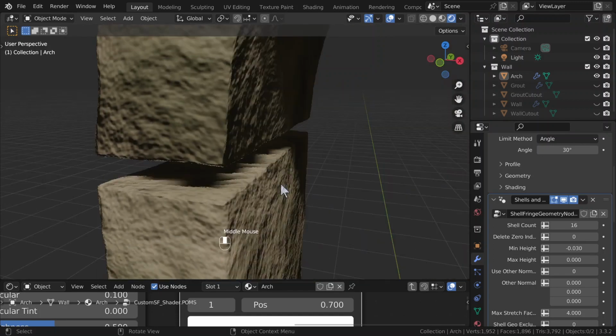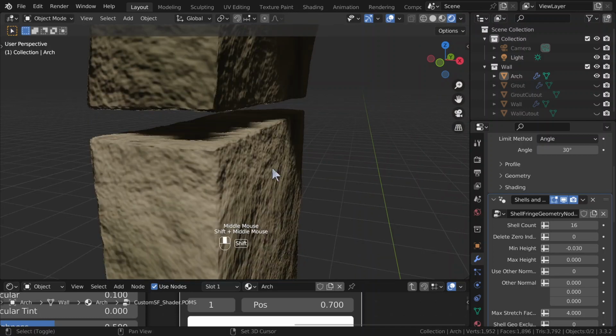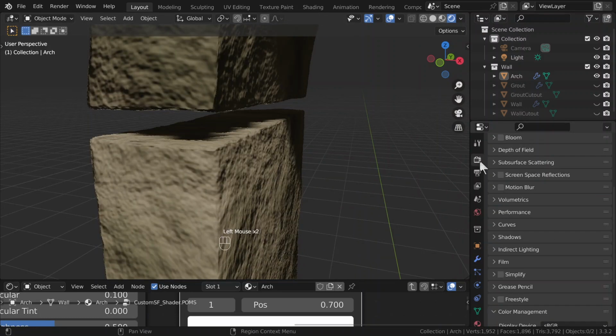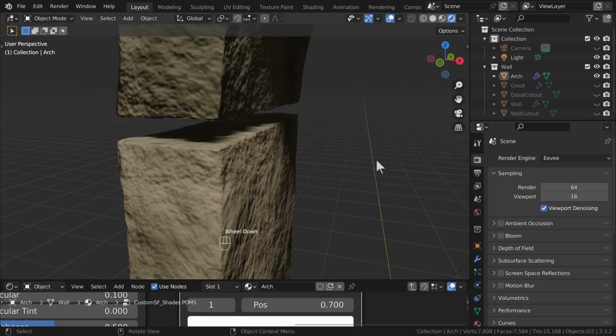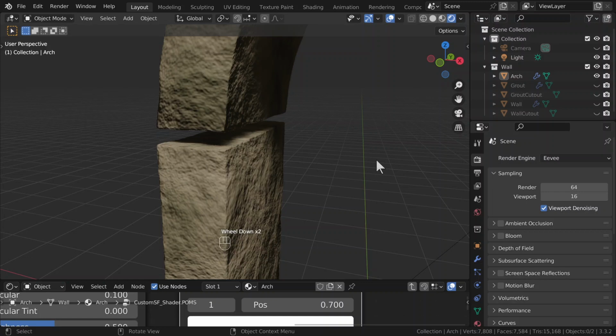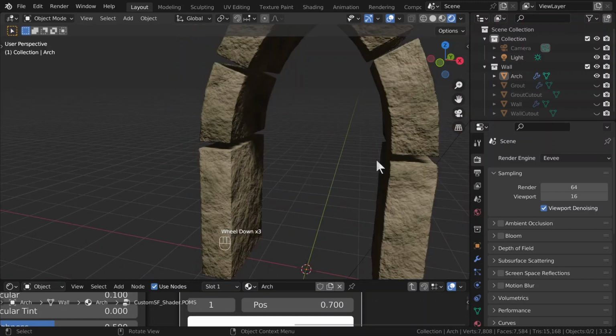Around the edges of the rendered geometry, I can see a bit of pixelation. I can fix that by increasing the number of samples. I right now have it set to 1 because I have a kind of crappy laptop, but I'll increase it to 16 so I can see what it looks like smooth. It blends in well. I'll go back to a setting of 1 for speed.